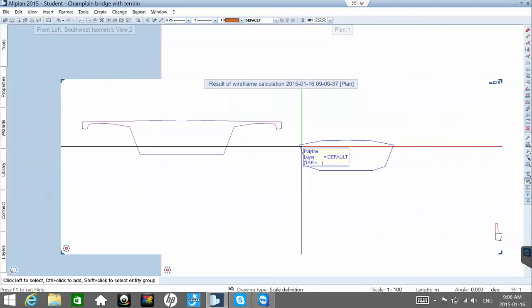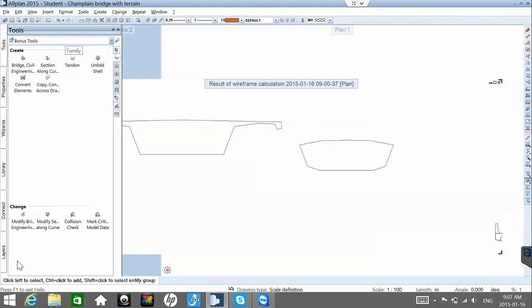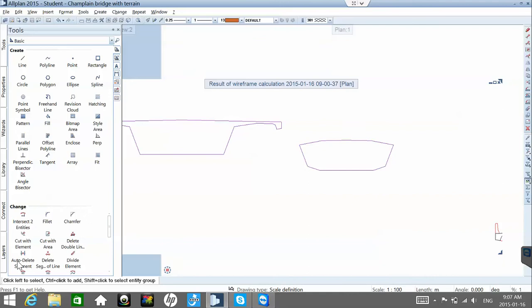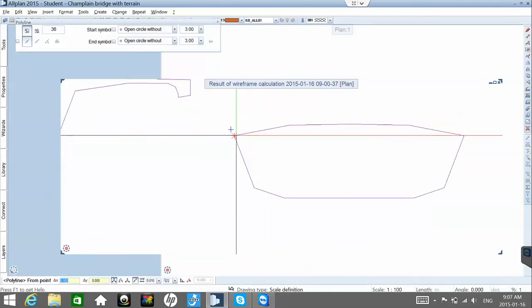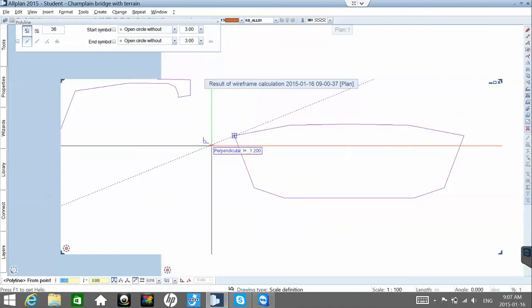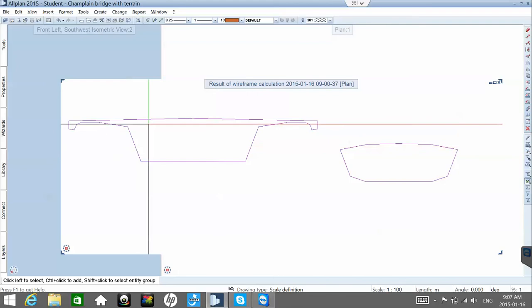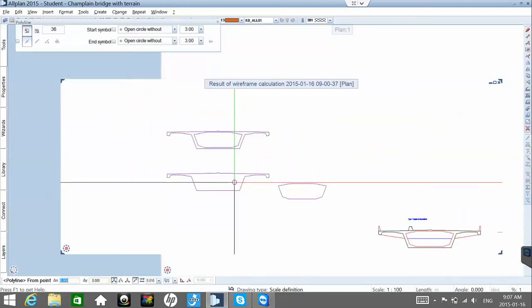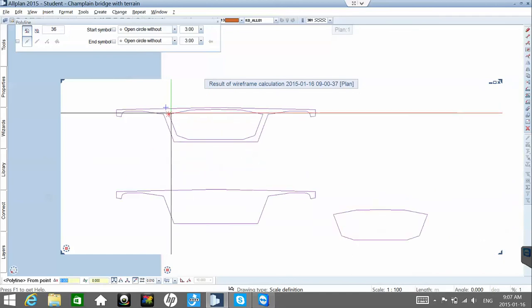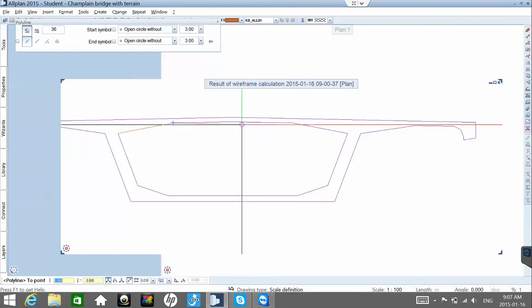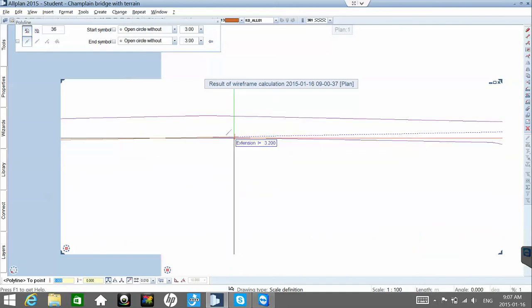go to tools, polyline, basic module, second function polyline. We have the brown area. No, not that one, the one above, because if you pick that one, we don't know where to place it. So draw over the one above, the upper cross section, upwards. Because after you draw it, we'll pick it from a known corner and attach it to the correct cross section.